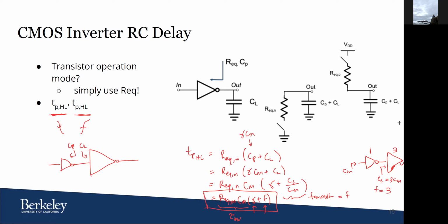I have a question. Is there no natural log of 2 term in the propagation delay? Yeah, there is, if you end up finding that exponential term. For the purposes of this, if I really want to be accurate, this is a time constant, so the TP would be ln 2 times tau. Okay, yeah, that makes sense.